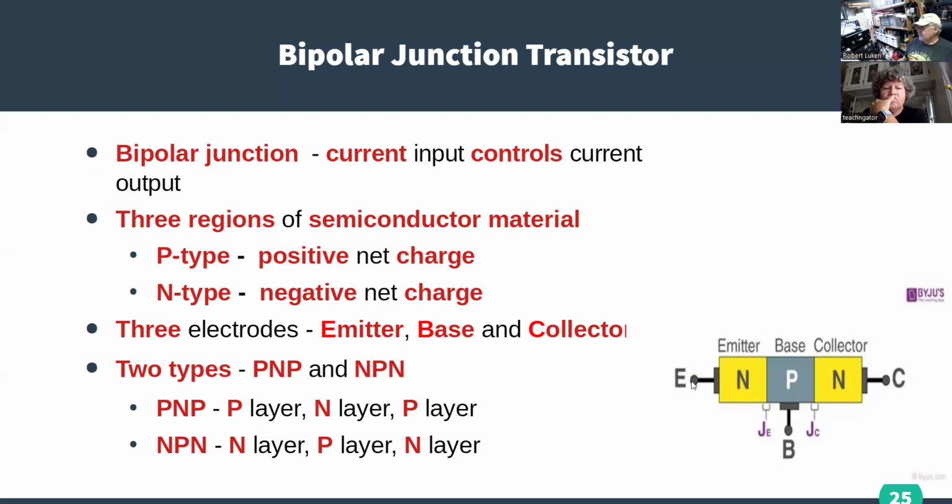So if there's a voltage between the emitter and the base, it will cause current to flow, just like this was a diode. This is a PN junction. So if we apply more than the threshold voltage, if this was a silicon device, once we get above 0.7 volts, this will start to conduct from the base to the emitter.